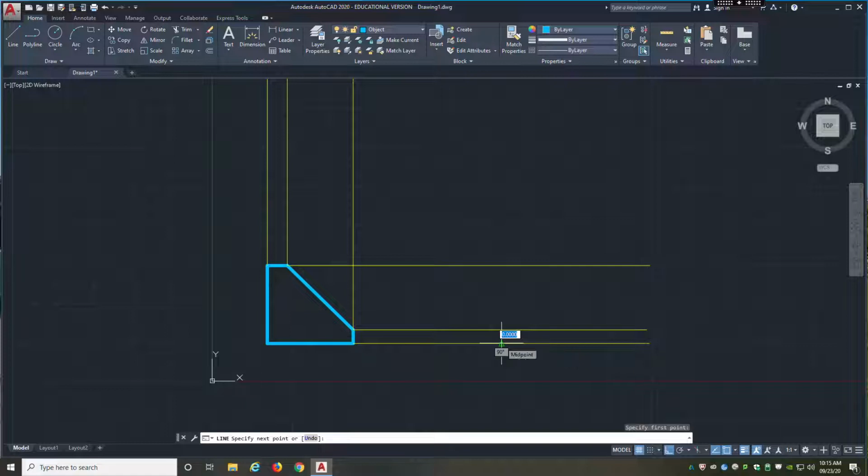Okay, so we're going to do this. I know I go up to here, right? And going across is 4.25, 4.250. Coming down, this is the beautiful thing about construction lines, is you know exactly where they have to go, without question, 9 times out of 10, right? Okay, so we've got this drawn, and I'm going to draw this line here at the intersection.